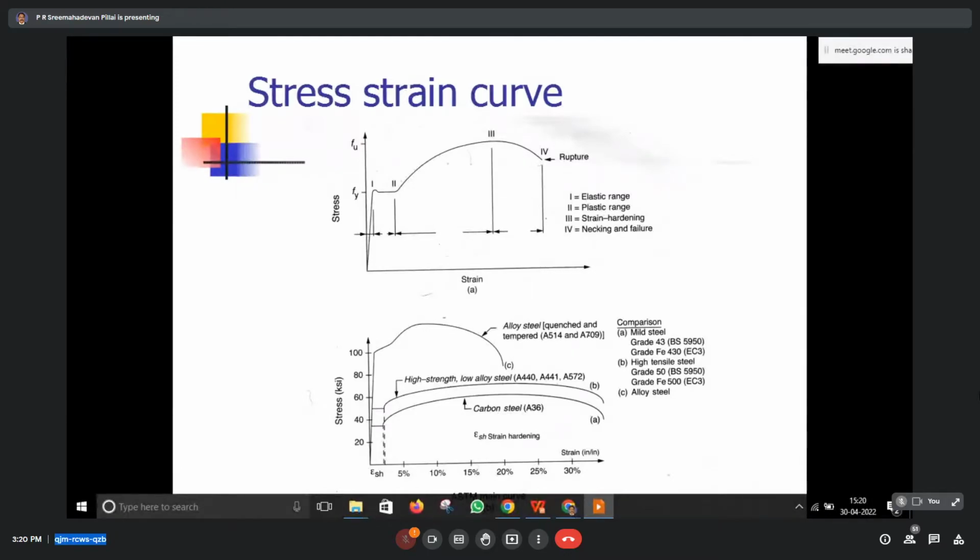Remember, based on the category of the steel, the stress strain behavior is different. This we always use in construction. From the construction point of view, mild steel is advisable in earthquake prone areas. Reason: mild steel will show symptoms of failure well in advance, whereas high carbon steel or HYSD bars will be more brittle and will fail more easily.